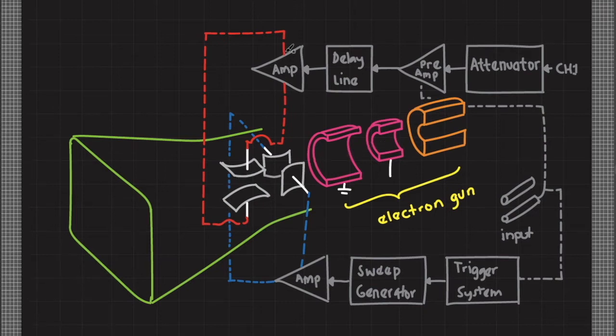So again, the electron beam is passed through these horizontal and vertical deflection plates, then lands on the fluorescent screen. The fluorescent screen usually has a phosphor crystal that gets excited and releases light energy when bombarded by an electron beam. So what you will see in an actual oscilloscope is a glowing screen, but if you adjust the intensity, then you'll be able to see a very fine line plot of the voltage versus time graph